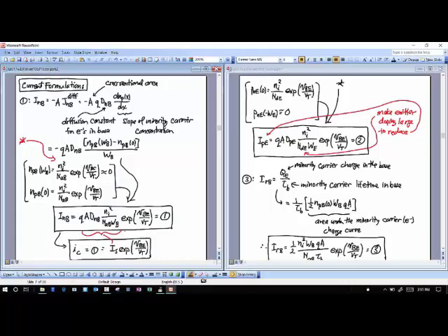The only difference is that in the IPE equation, holes in the emitter, I'm using the emitter width, and I'm using the concentration NDE in the emitter instead of the concentration NAB of acceptors in the base. Okay? Now there's a big difference here though, because this concentration NDE in the emitter is much larger than this concentration NAB in the base. Okay, remember that. Because what that means is that this current IPE is much less than this current INB, which is exactly what we want for reasons I will show in just a second.